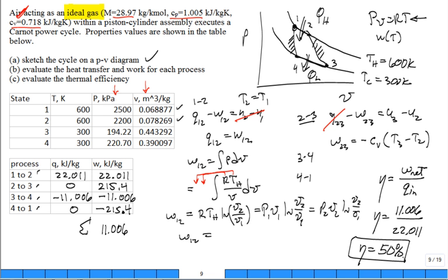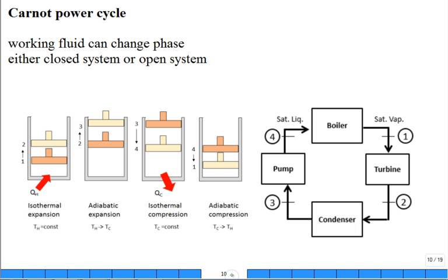Somebody says, is that consistent with the equation that you just showed a minute ago, which was for any Carnot heat engine, the thermal efficiency is equal to 1 minus TL over TH, 1 minus, in this application, 300 Kelvin divided by 600 Kelvin? This is one of those surprising things. All of that work, if I didn't drop any digits, gives the same answer as that shortcut, 1 minus TL over TH. It's pretty profound, isn't it? I remember when I first was like, what? My jaw dropped. Does this really work? Somehow it's magic. But no, it gives you the 50%.